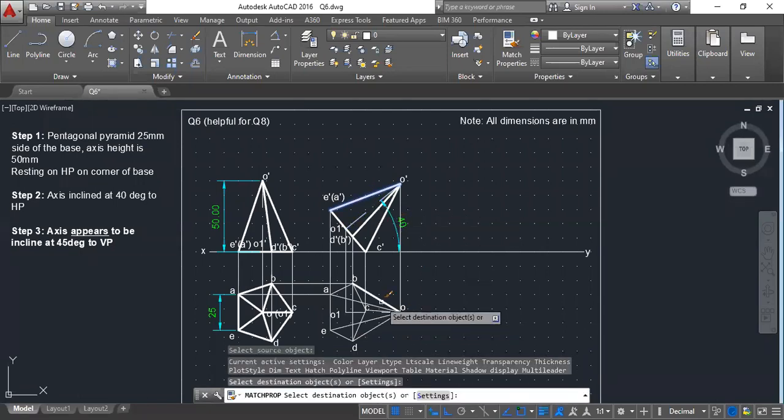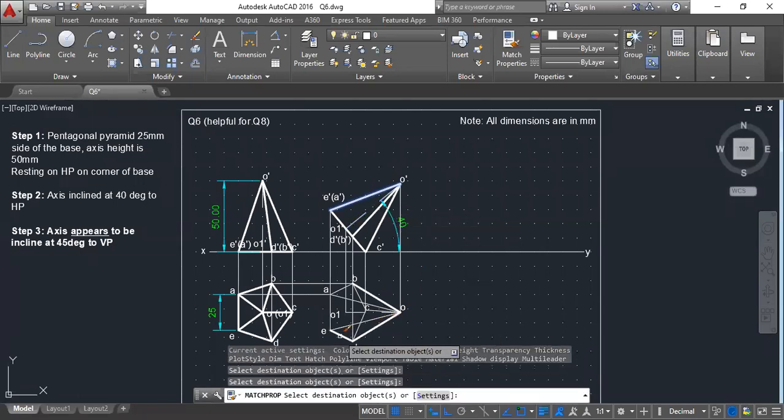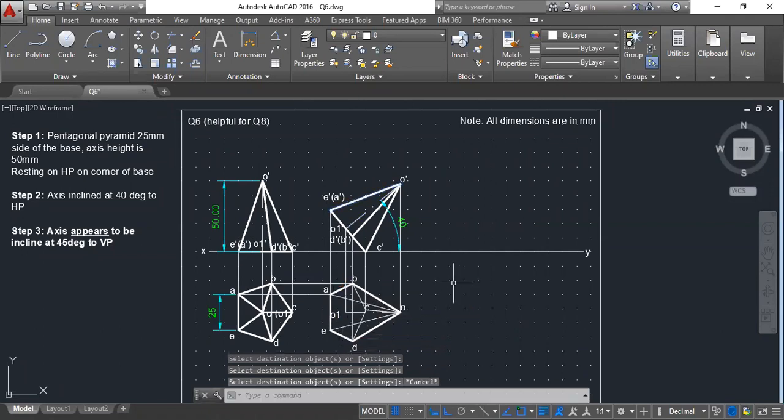The next thing you can do is make all the outer boundary of this figure dark, I mean continuous and dark. This step is simple. Now whatever lines are remaining, we have to think about those lines. First let me think of the line OA. When I'm drawing the top view, remember, imagine as if you are seeing from the top.